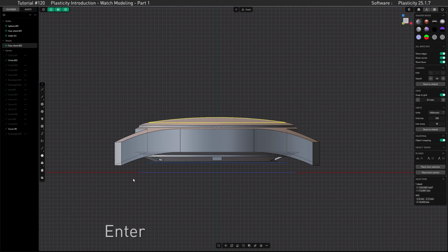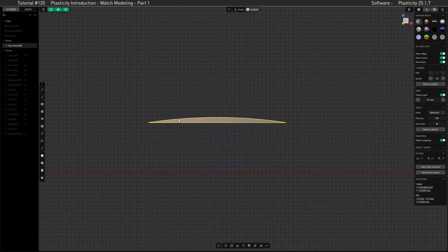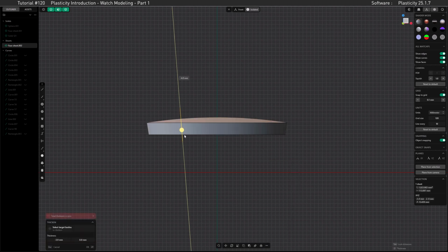Here we go. Let's give this glass some thickness, as this is needed to make it render realistic. And while doing so, introduce you to a new command. So if we select the glass, we can solo it by hitting the dot key, but not as in Blender on the numpad, but on your keyboard. If you think Thicken tool, good call, but unfortunately, since this is part of a sphere, it is tapered.